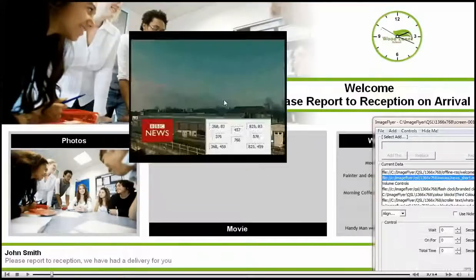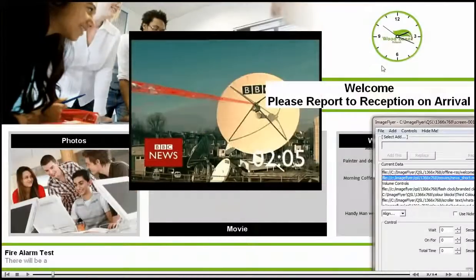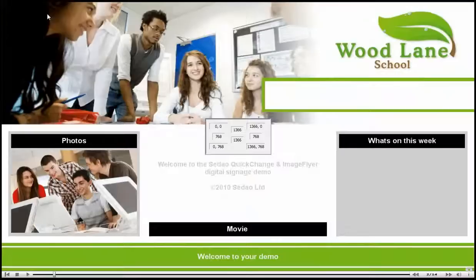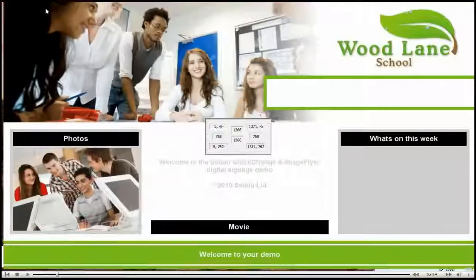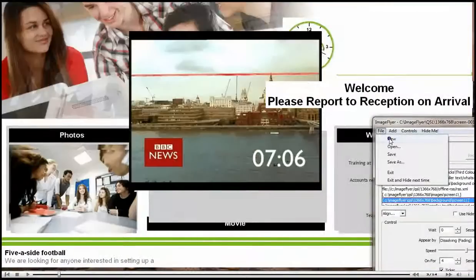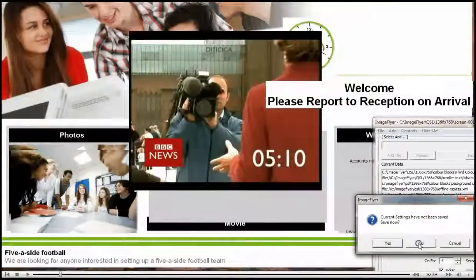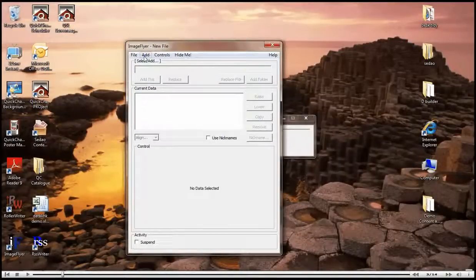All zones are added as layers to your computer's desktop. Move zones by dragging them with your left mouse. Resize zones by dragging them with your right mouse. Position them where you like at whatever size you like. To start from the beginning, select File, then New from the menu on the control panel.